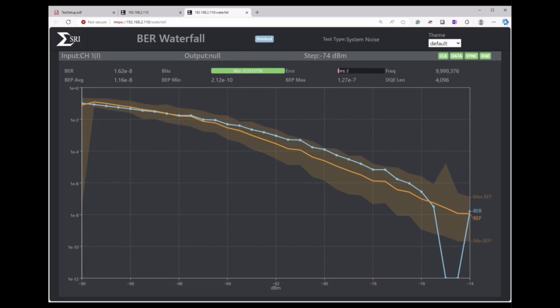Okay, now we've finished with our test, and we see it tracks pretty closely. As we've gotten to the higher data rates, the quote-unquote measured bit error rate is really just an estimate. Technically, to get a correct bit error rate, you'd have to let that test go on forever. Since we don't want to wait forever, we put some arbitrary limits on that.